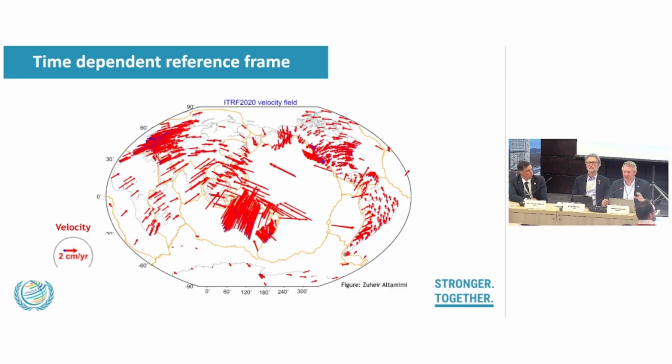But then there are other systems like intelligent transport networks, as I said. If we didn't have a time-dependent datum and people are using GPS information coming through to keep their cars on the road, if we didn't update it every couple of years, cars would start to move into the wrong lane or onto the wrong side of the road. So you need to make available different datums depending on what your user requirements are.